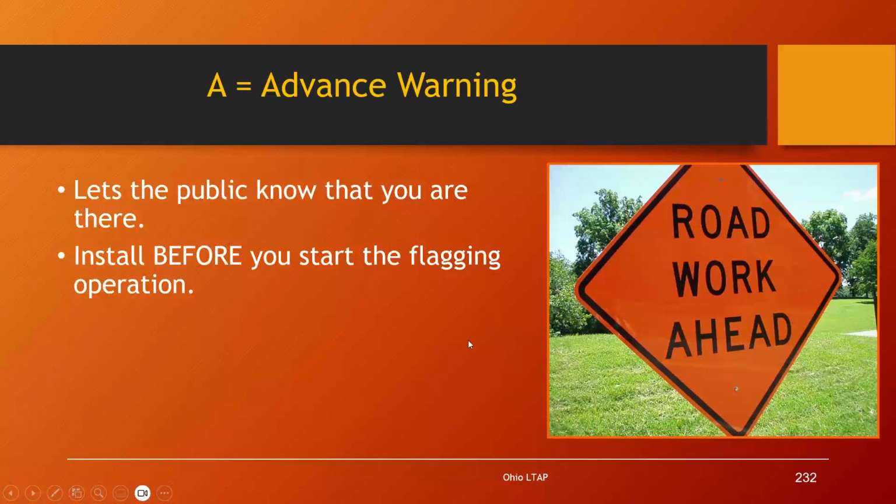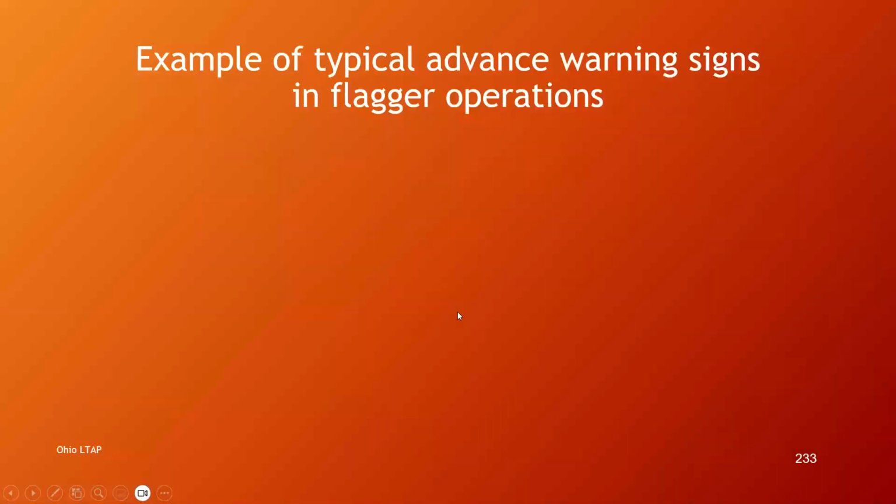The advance warning area lets the public know that you are there. We definitely do not want you to be flagging without the proper signs that alert the motorist that there is a flagger ahead. So this needs to be installed before you start the flagging operation.